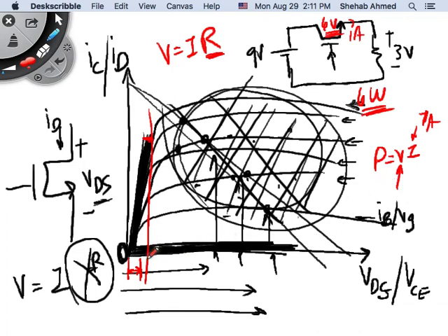Here we were talking about what? You remember what it was for the MOSFET? This was the threshold voltage, or when the device was point something, right? 0.2, 0.3 volts was when your device was going to be going into triode region. If you remember, the boundary between the triode and cutoff was about 0.3, 0.4 volts for a MOSFET. You were talking about much smaller. So here you're talking about, let's say, 0.3 volts. 0.3 times 1 amp is 0.3 watts. So 0.3 watts versus 6 watts of loss in that case, right?